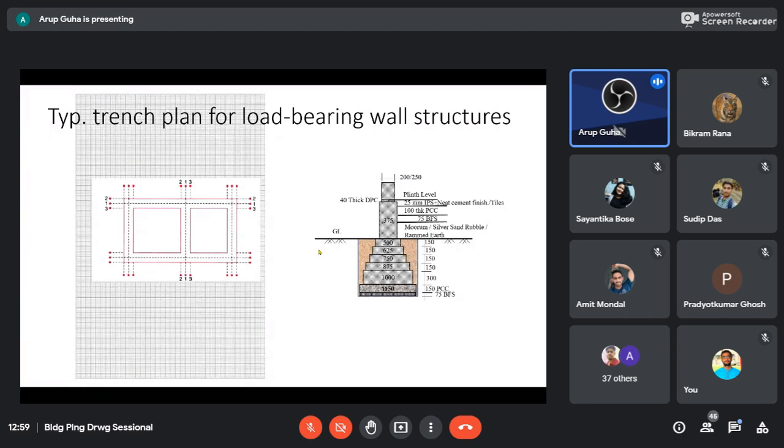That actually depends upon the bearing capacity of your soil. So that is a calculation that you will learn. These dimensions are only to give you certain ideas. Okay. Everything is mathematical. Nothing like thumb rule. The capability of your soil will govern how much width you have to provide.